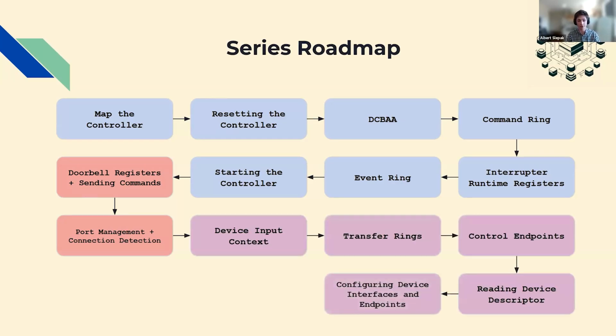Then it will be the hardest part and probably the longest videos, which will cover taking a connected device and fully setting it up, identifying what kind of device it is, setting up the input context, all of the transfer buffers and rings, control endpoints, and reading the device descriptor, which tells you what kind of device it is, the serial number, the power management settings, etc.